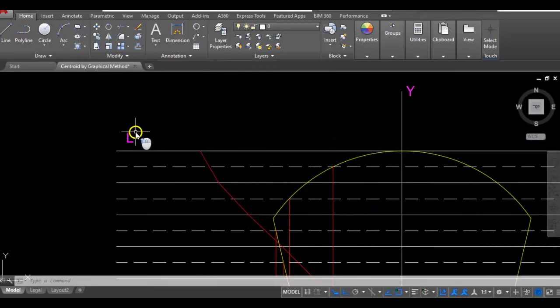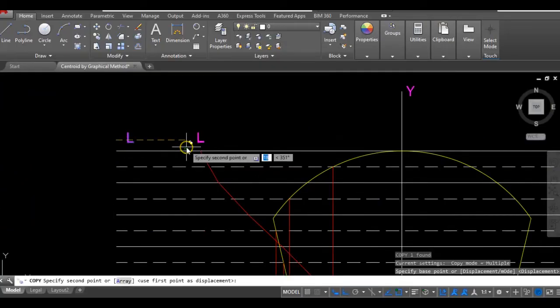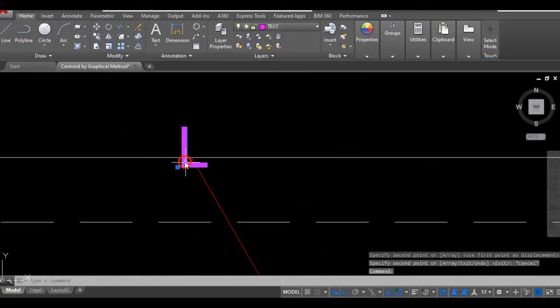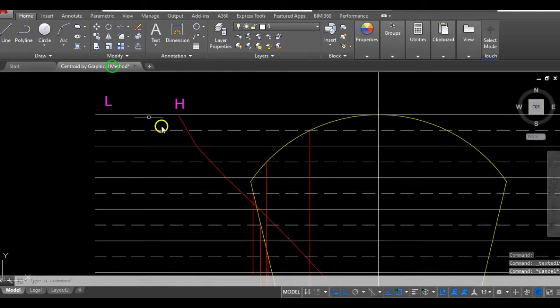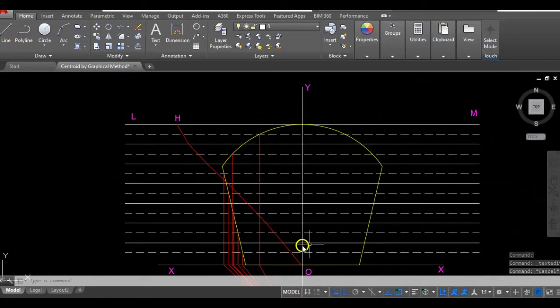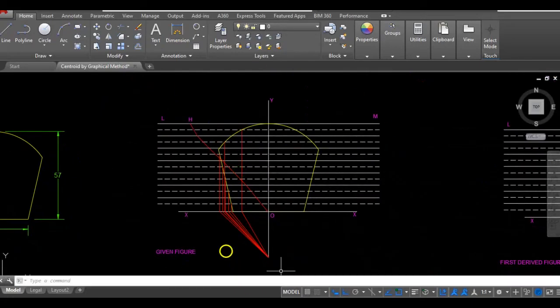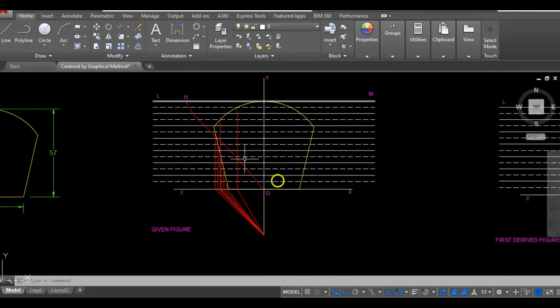So now what I'll do is just put a label here for where it ends. And I'm going to name this H. Just me giving a letter. So that's where our funicular polygon is. So now to determine the area of the shape, what is done is that we find the width of the funicular polygon and we multiply it by the height of the pole. So that's how the pole comes into play.